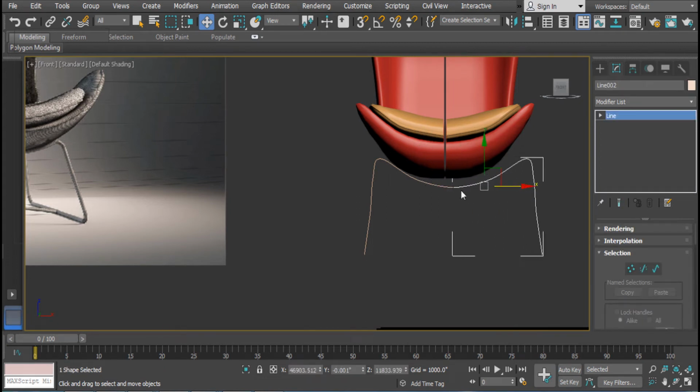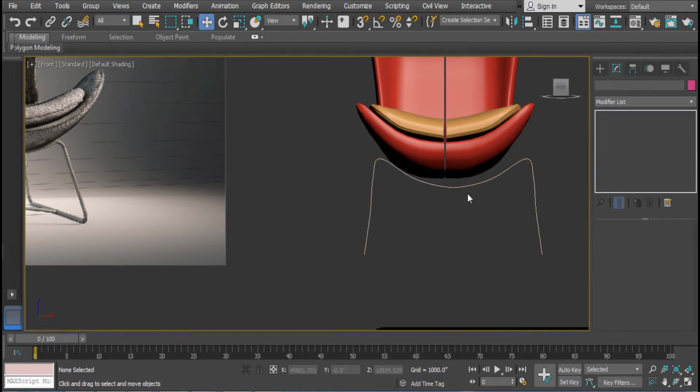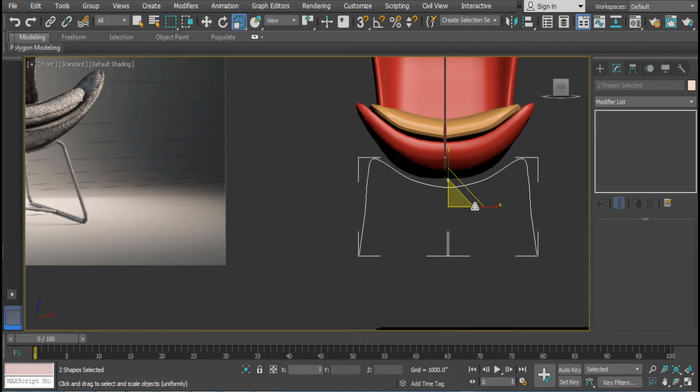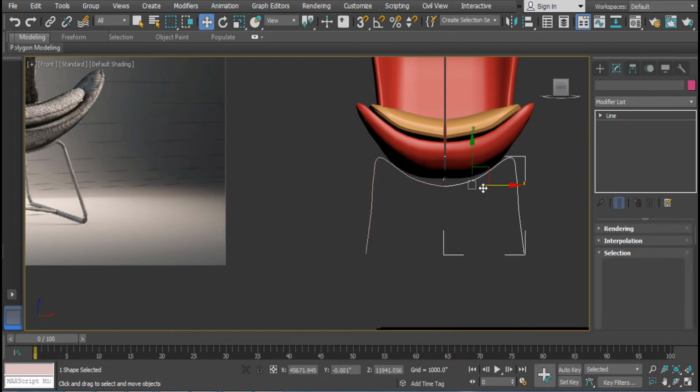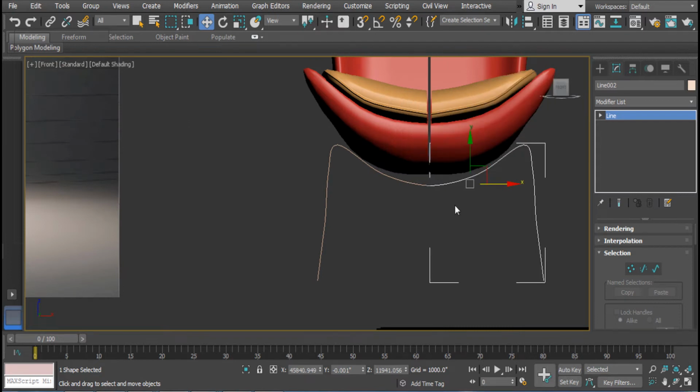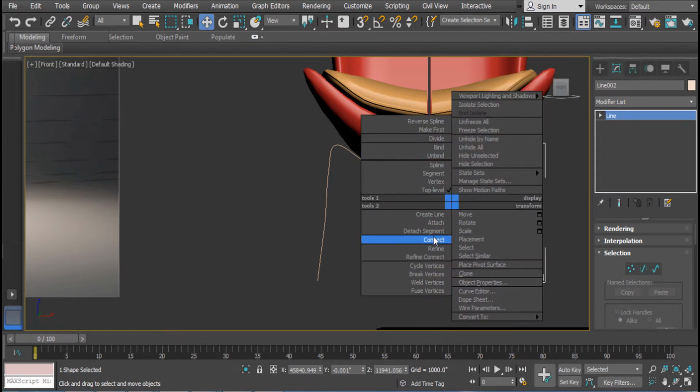So no need to work with the complete one. Work it up to 50%. You can use the mirror option and take it as an instance. Instance is the better one. Also move the vertex almost to the center of the object. That is easier to make.